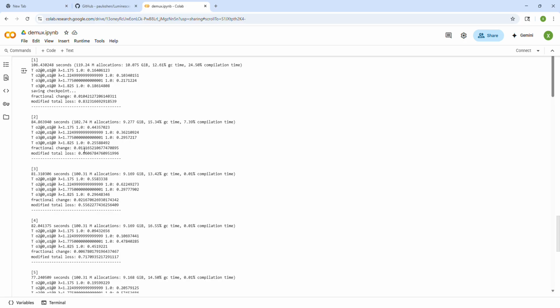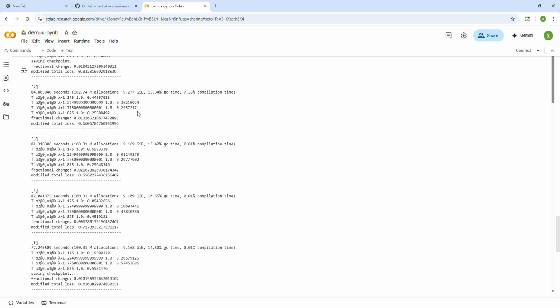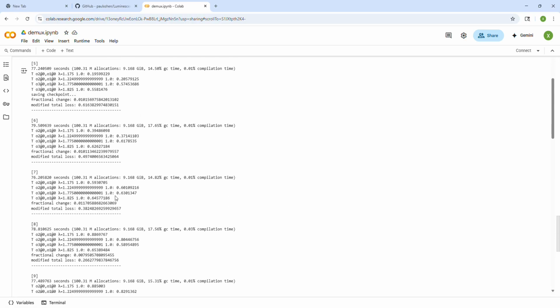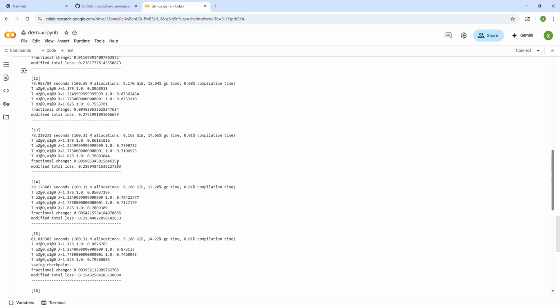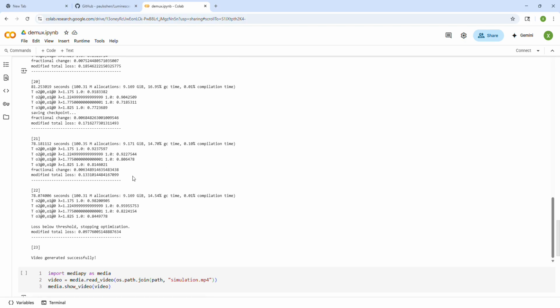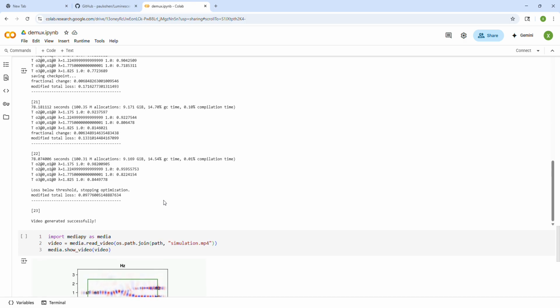In each iteration, I can see the time. I can see how the design is doing with respect to our different targets. So here are the four T parameter targets around the different wavelengths. Ideally, they should be 1.0 in our case, but at the beginning, I'm getting much less than that, right? From the initial geometry. So as we go through the optimization, you can see the targeting improve. Yeah, so this is pretty quick. It only takes like 20 iterations to reach a 10% target, and this thing stops automatically.